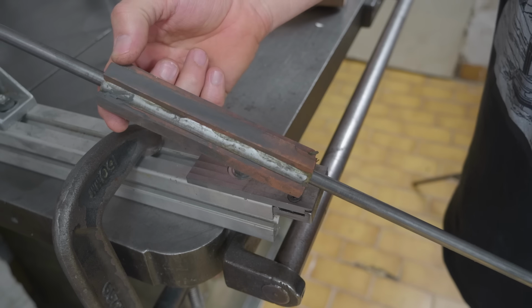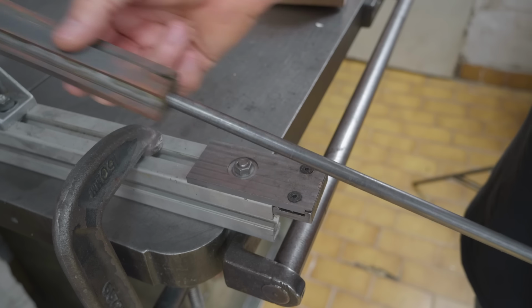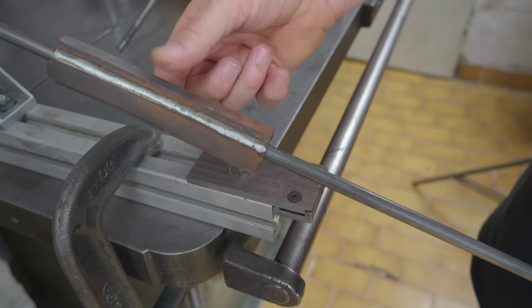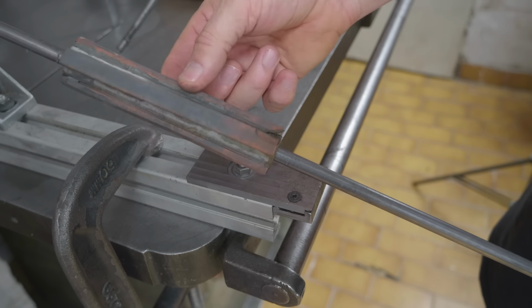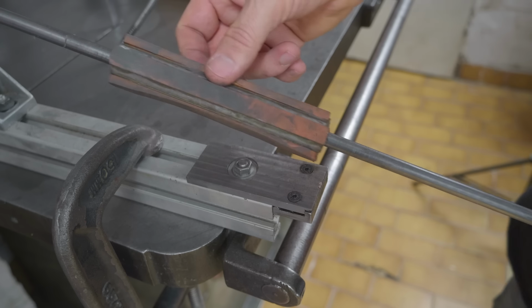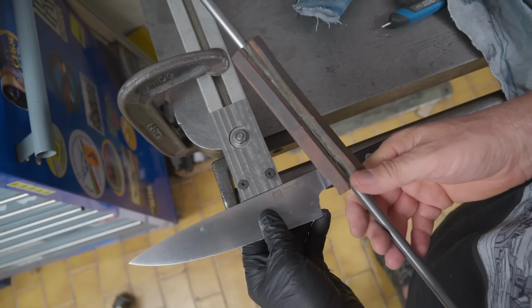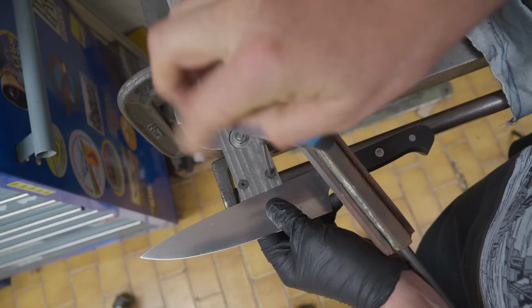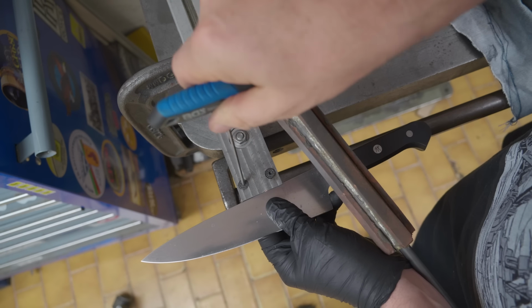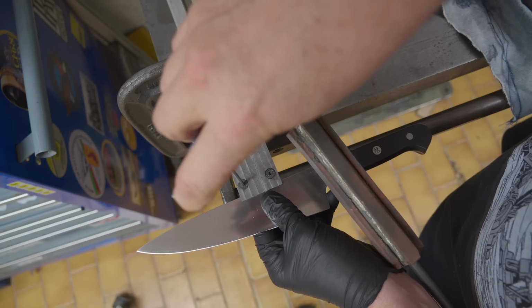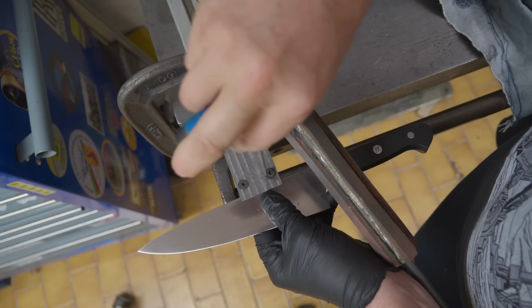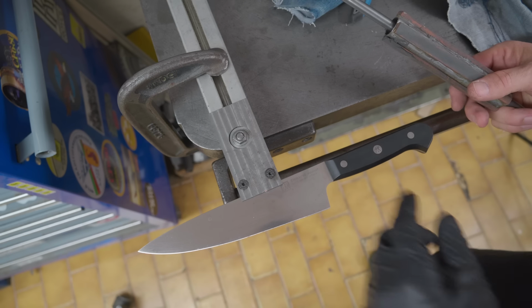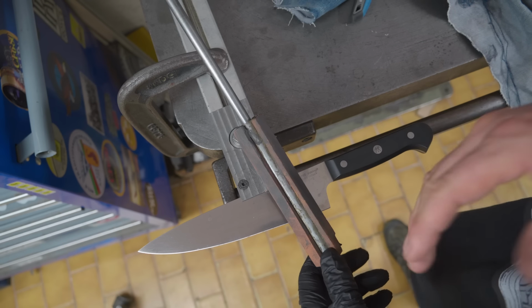I took a piece of water pipe, turned both ends to fit linear bearings, and then just epoxied 4 different grits of stone onto the outside. As you can see, they're starting to look pretty worn by now. Should probably get some new ones. I realized after I'd made it that this is probably not the most convenient mounting method. I've since seen that the better versions of this mount the knife on some sort of a system which you can flip over, so you can do both sides at once. I have to do one side at a time.